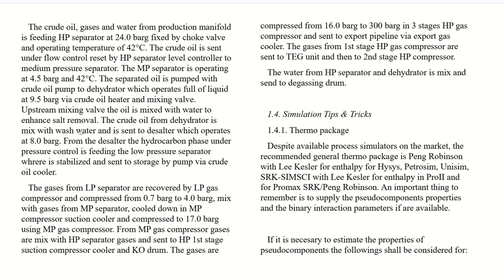And there is a spec actually. You have to find it in the Saudi Aramco standards. What are the crude oil specs after the desalters? 0.5 ppb salt content, and RVP close to, I think, 10 psi or something like that.